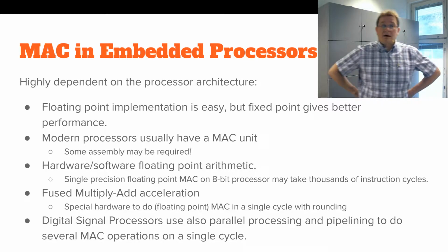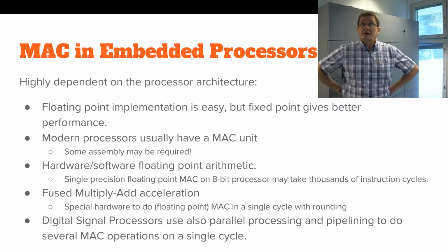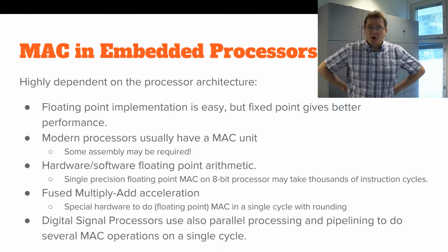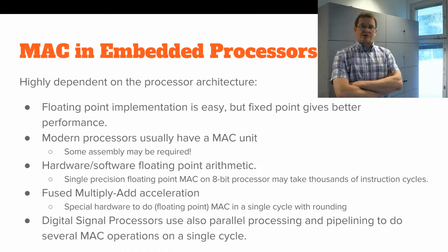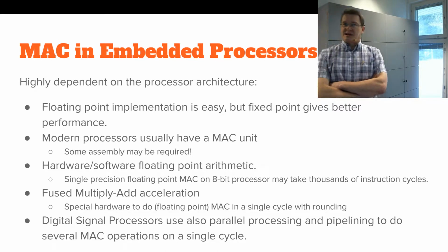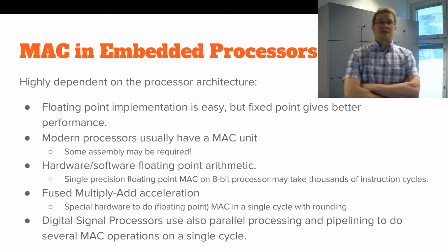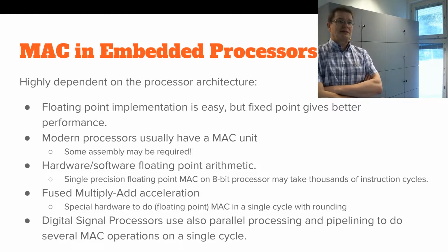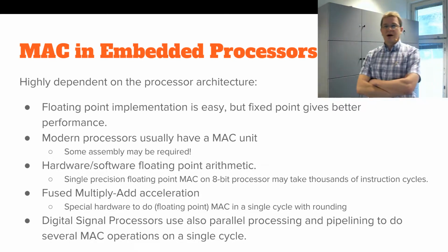Okay, and then there are actually some special things, since those digital signal processing tasks are quite common on embedded systems. Some of the embedded controllers have so-called fused multiply-add acceleration. Basically, it's just special hardware to do that floating point multiply-accumulate in a single cycle with rounding. Basically the chip designer has already decided how to round these numbers,